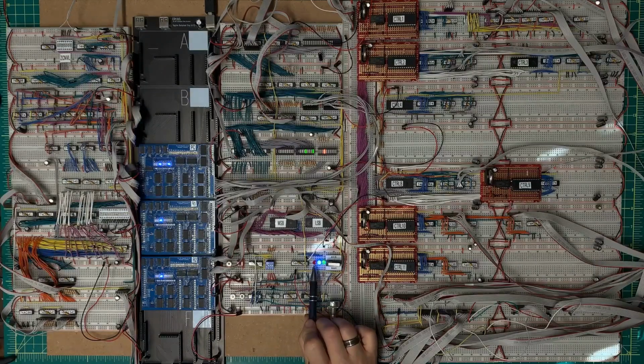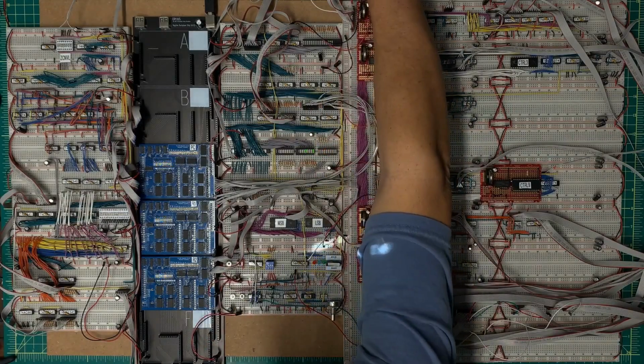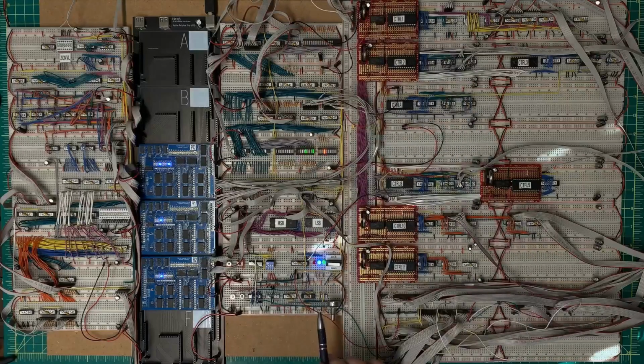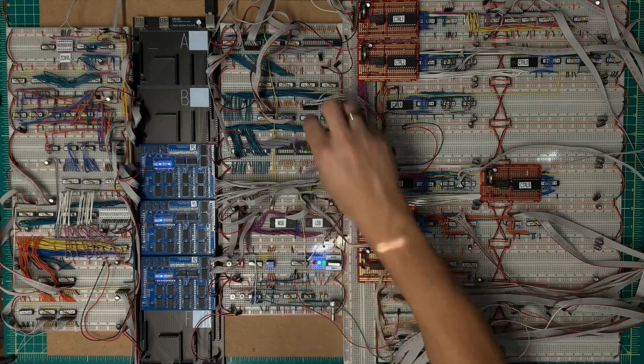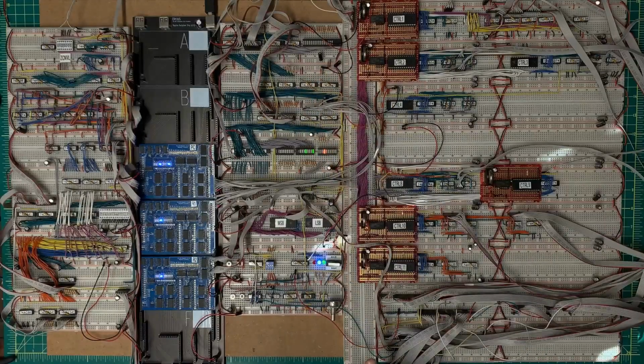I'm still paying close attention to this voltage concern. This is also a reset. So once things are in reset, when I power up, it's taking a little bit for that to settle down. I believe a lot of it is due to all the capacitors I have on the board that need to charge up. I have a feeling that my power on amperage is very high, and I am likely going to need some sort of a soft start mechanism, but that's not for today's video.